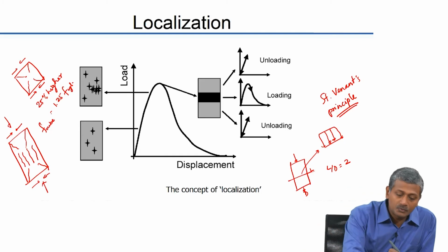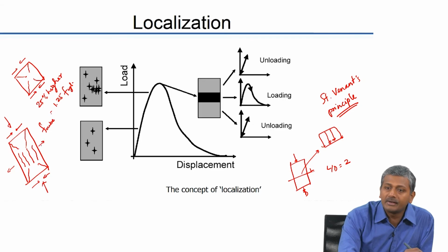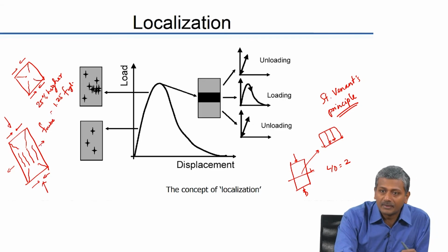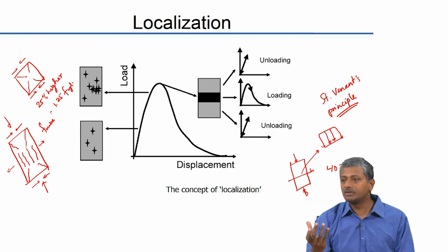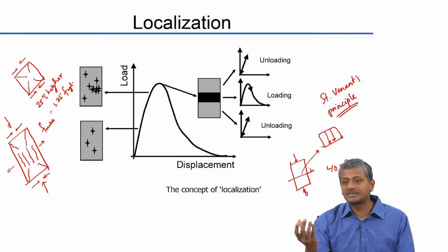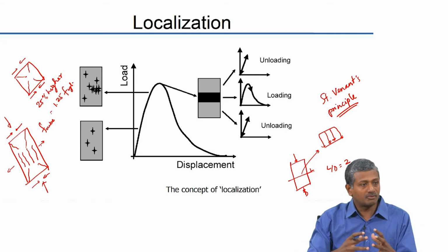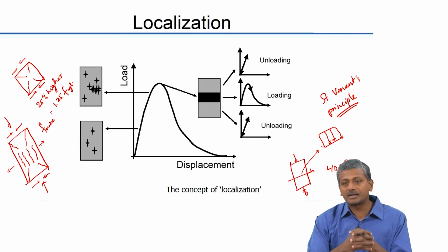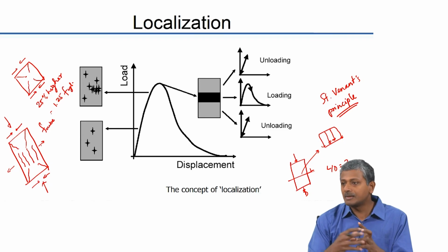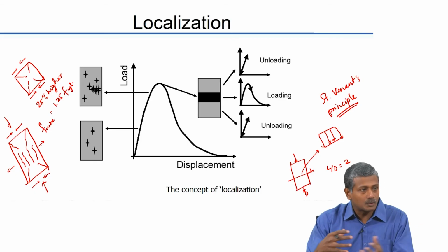So essentially this vertical crack means that the tensile strain capacity in the lateral direction is getting exceeded, okay. In true compression, how will the failure be? It will be crushing. So your concrete should turn into a powder. So for example, if you do a triaxial compression of concrete, you will not see any of these cracks developing. So beyond a certain point of time, the concrete should just crumble into a powder. For example, when you do concrete testing under hydrostatic conditions, so all stresses are equal in that case.